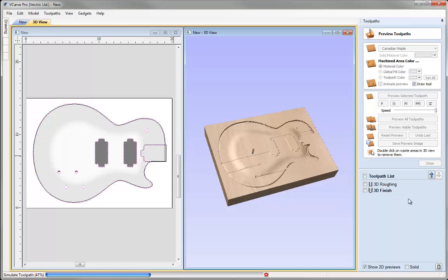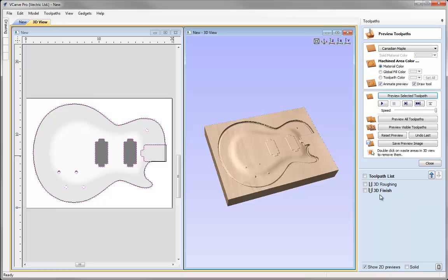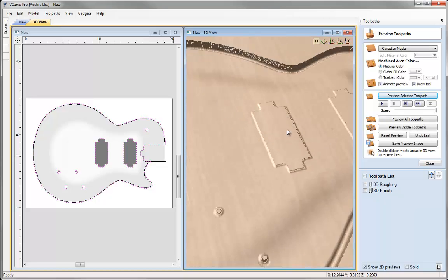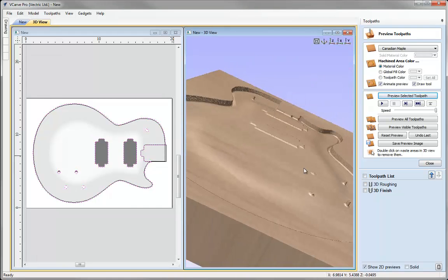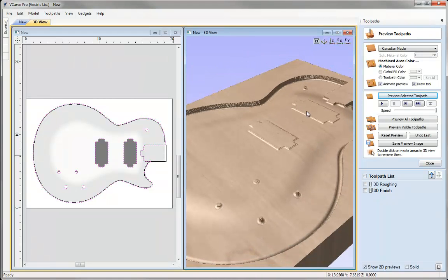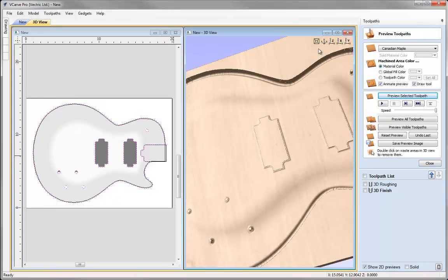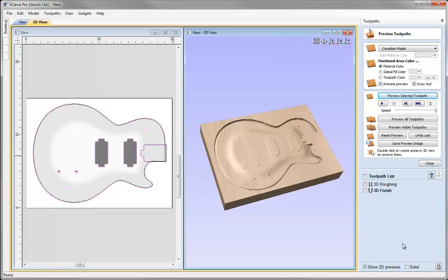We might benefit from switching off the tool at this point to go a little bit faster. It's not too bad, still pretty fast within the software. If we look there, now you can see what our machine surface is going to look like, and we're still left with some material in the areas that we haven't cut. And now what we're going to do is go ahead and create 2D toolpaths in order to machine those areas much more efficiently and provide ourselves with a much cleaner edge than if we'd allowed the 3D toolpath to go up and down into those parts.